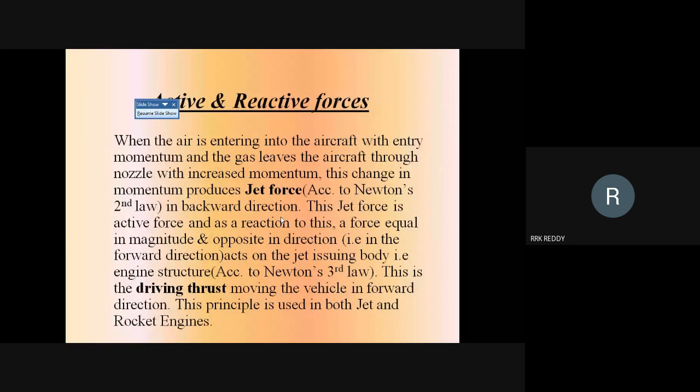So what are the active and reactive forces? When the air enters the aircraft with entry momentum, and the gas leaves the aircraft through the nozzle with increased momentum, this change in momentum produces jet force. This happens according to Newton's second law. This force is developed in the backward direction of the aircraft movement. So this jet force is the active force, and we treat it as the active force.